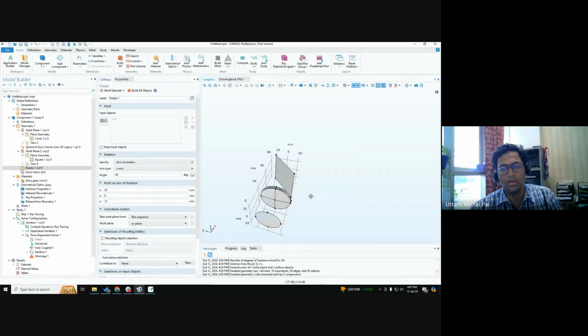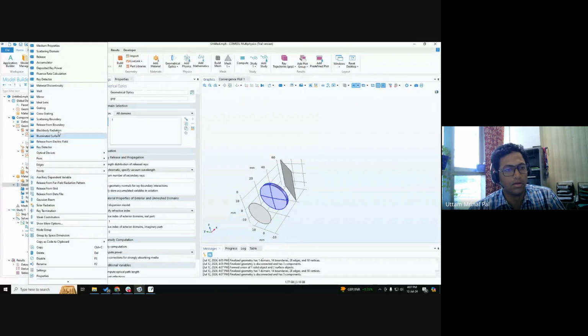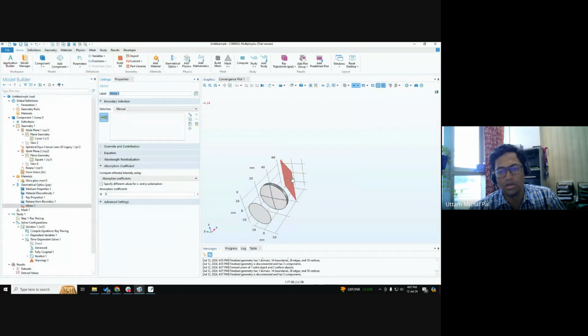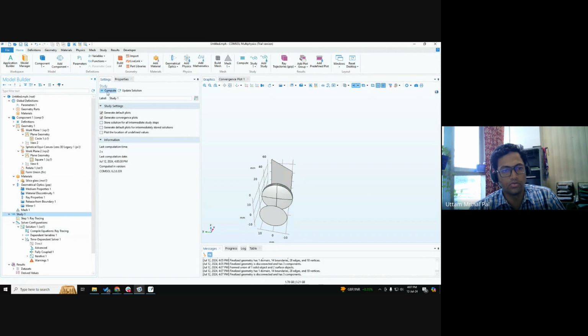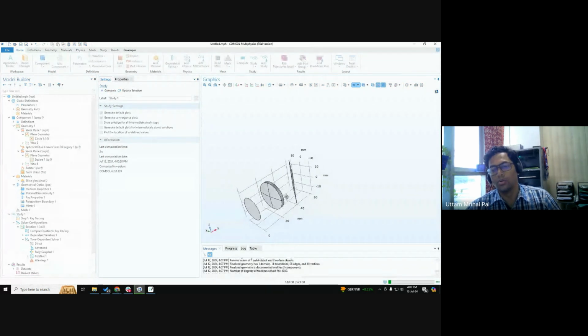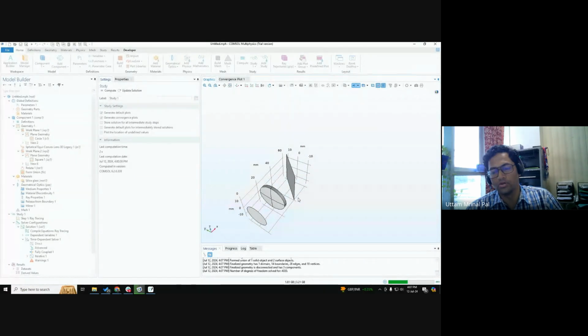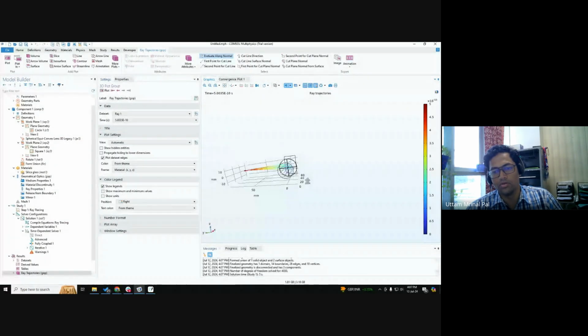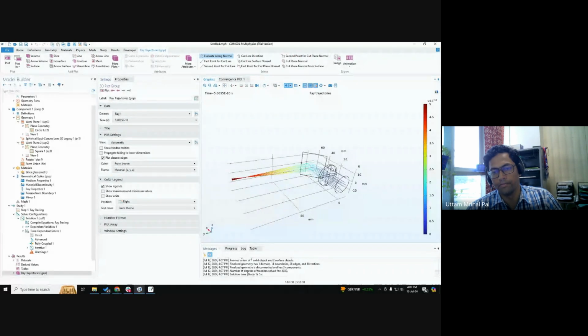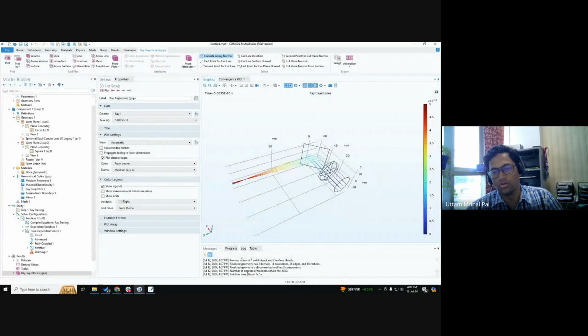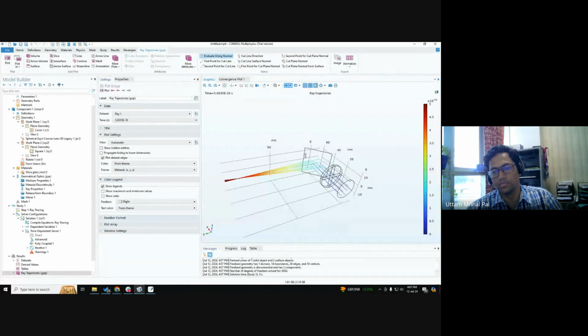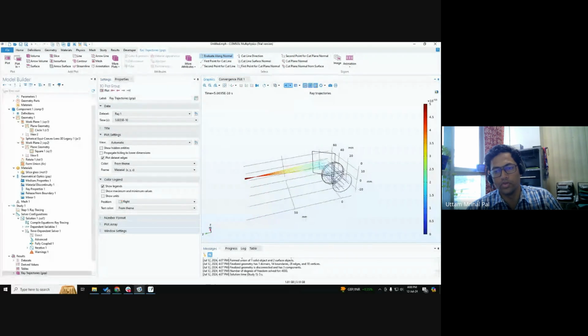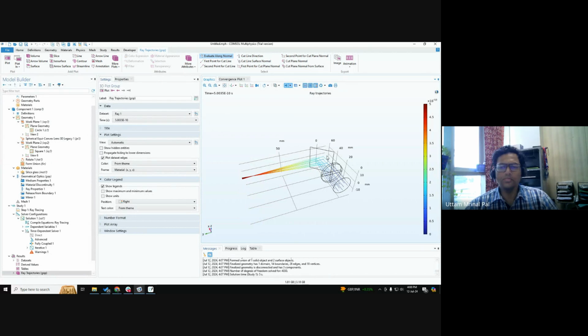So now, for example, I can start with a simple mirror. Okay, so I will use a mirror operation and then just apply it to this boundary. Let me just try to solve this first and show you how it works like a mirror, and then I will go ahead and show you with the dichroic mirror. So now you can see that you're launching the rays from here, going through the lens, interacting with this mirror, and then focusing over here, right? But here it is allowing the light through at all the wavelengths.